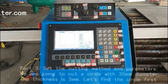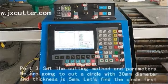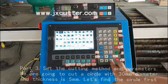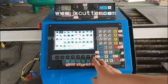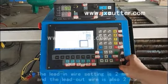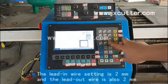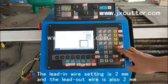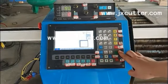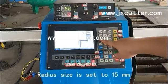Part 3, set the cutting method and parameters. We are going to cut a circle with 30 mm diameter and thickness of 5 mm. Let's find the circle first. The lead-in wire setting is 2 mm and the lead-out wire is also 2 mm. Radius size is set to 15 mm.